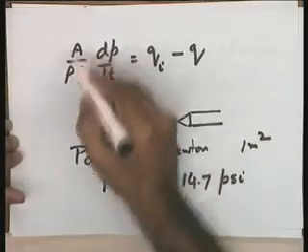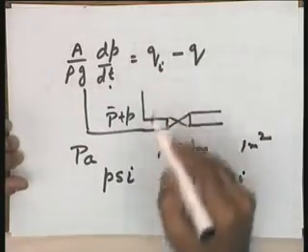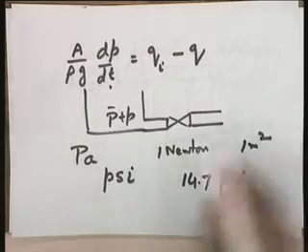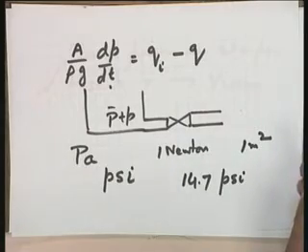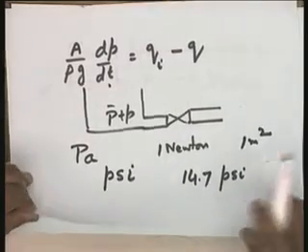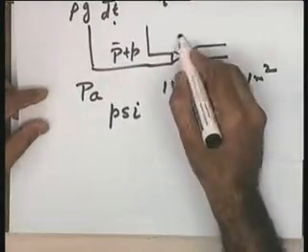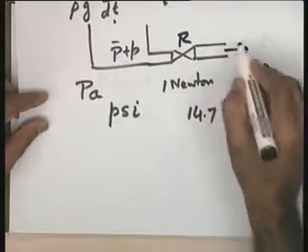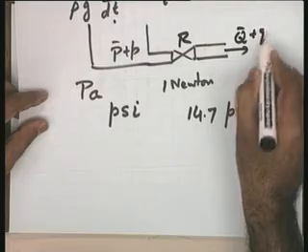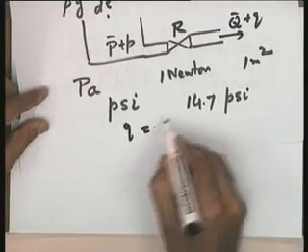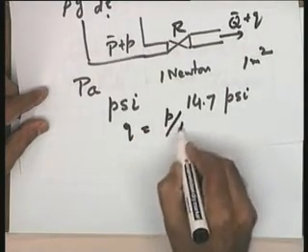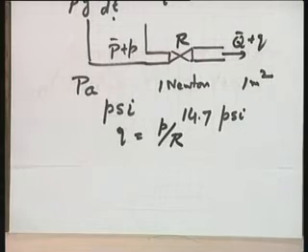So, if all the pressures in the system are in terms of gauge pressure, in that particular case the reference is atmospheric pressure, and hence I can write, as far as this particular unit is concerned, if R is the resistance and Q is the flow, Q bar plus Q, please see my equation, Q is equal to P divided by R. You have to agree to this equation, where P, this has to be very clear, has to be gauge pressure.